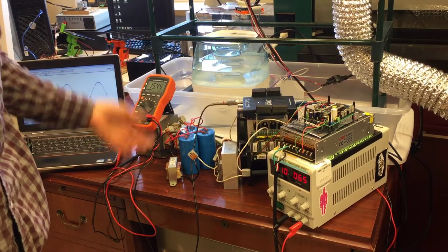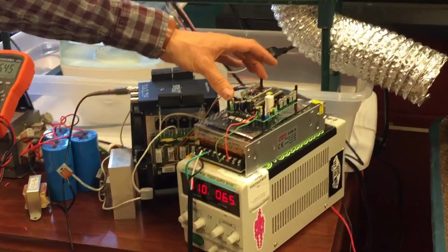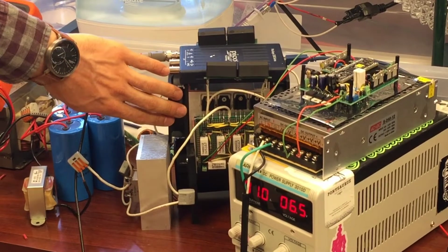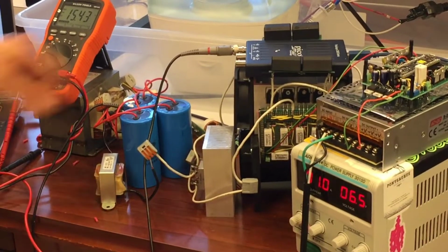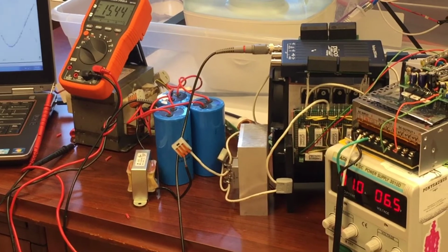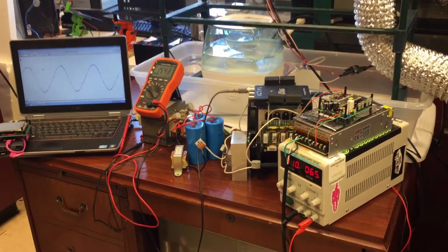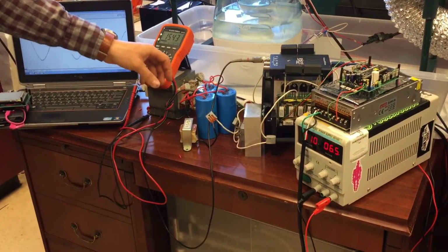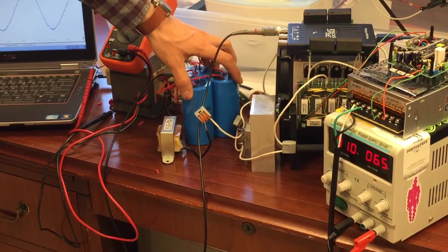Okay, so this inverter works off of the logic constructed here on an FPGA converter circuit. It amplifies to an IGBT inverter. There's another side on the other side of the heat sinks here. The technique I used was voltage cancellation PWM, which is derived from a phase shift between the two bridges. The filter that I have developed starts with rectification and then goes through an LC filter.